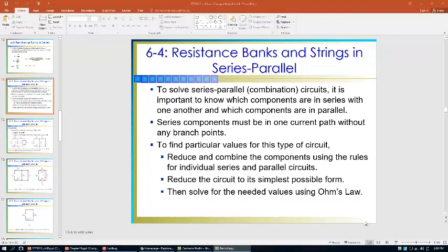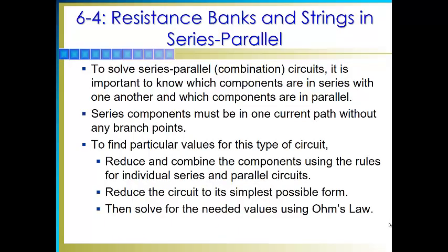So to solve series parallel or combination circuits, it is important to know which components are in series with one another and which components are in parallel. Remember, the series component must be in one current path without any branch points. In other words, the components must be on the same line, one after another, with no other branches coming out of the segment.